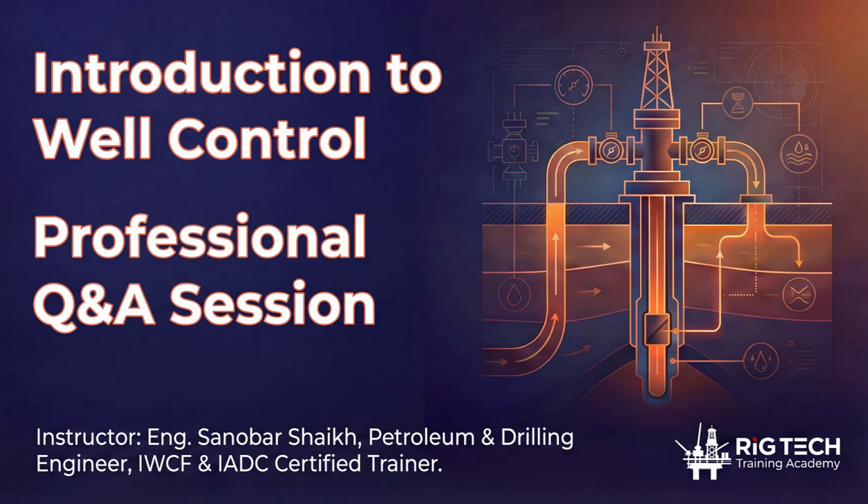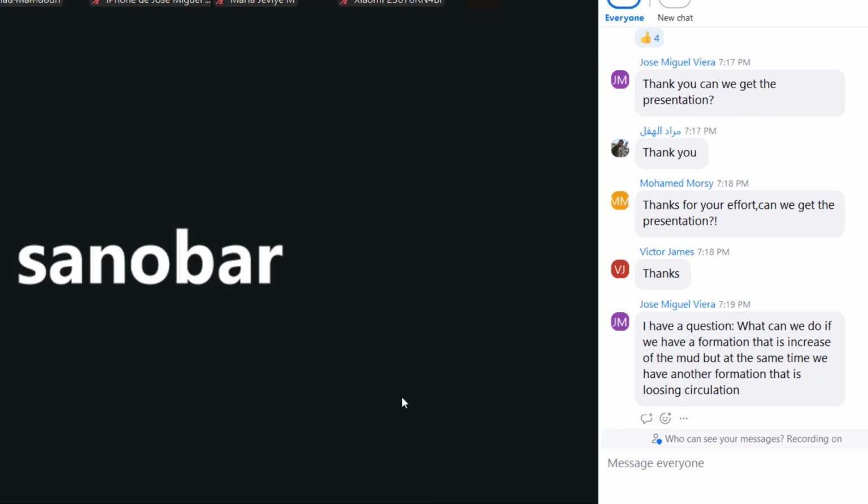There is a question from Engineer Joes in the chat box. Okay, let me see. That I have already answered. What can we do if we have a formation that is higher than the mud weight, but at the same time we have another that is losing circulation? This we have answered. We can isolate those formations by setting casing.